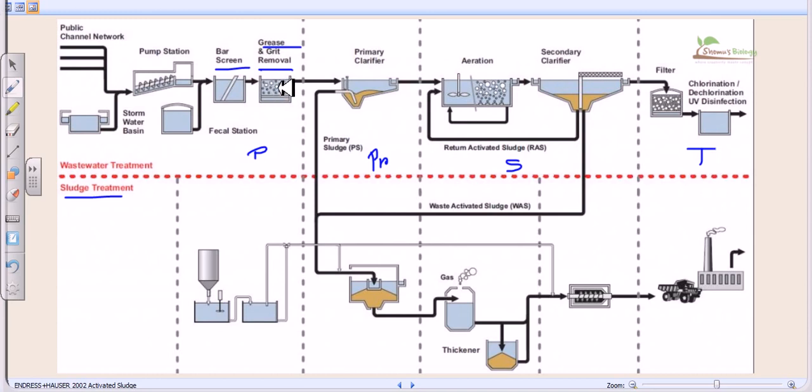Now we take up all these things with the help of scum removal, and we leave them aside, and it will remove all those grease materials, and right after that we end up with the water, and in the water we have small particles of other nutrient sources, but not the bigger particles, because all the bigger particles are removed in the bar screens and the grit removal system of preliminary treatment.